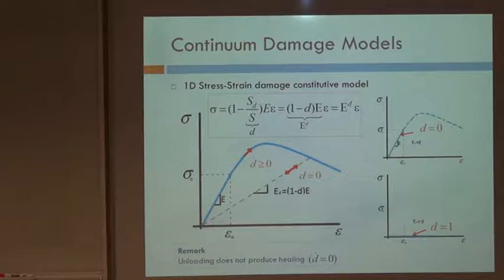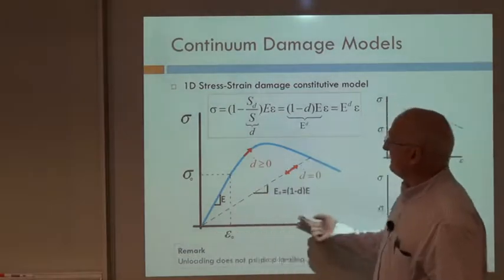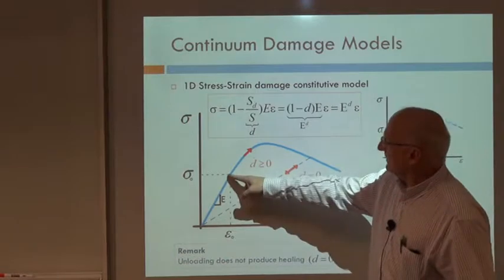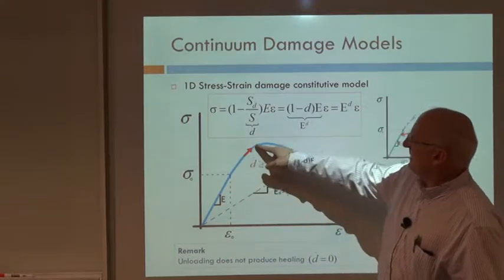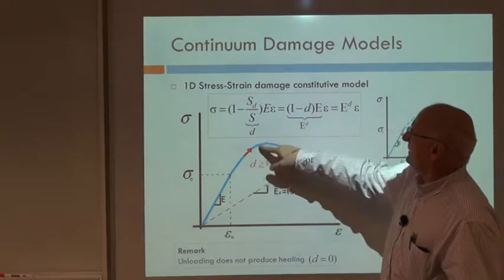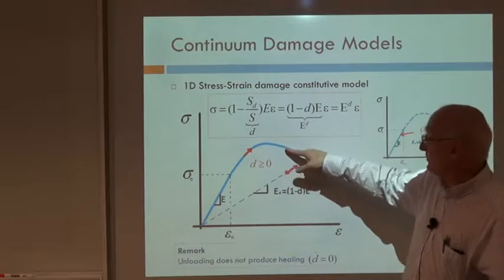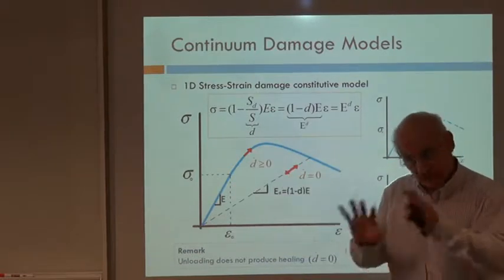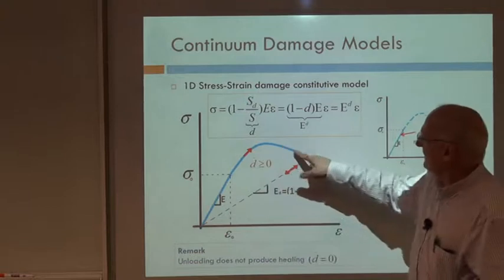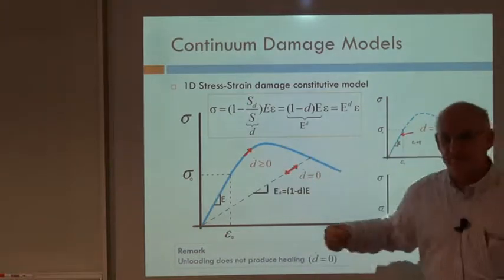Okay, so this is the plot. Look, another question is the following. What happens at a certain point, when I increase the strains? Imagine I increase the strains, the material reaches this stress, then maybe it can go this way, but we'll talk about that too. The material at a certain point decreases its stress capacity and goes this way. That's what we call a softening branch. We'll talk about that.